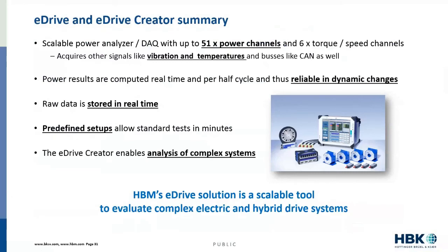So the eDrive creator really takes HBM's eDrive power analyzer another step forward in making it even simpler for users to do high-end measurements on complex systems without having to spend a lot of setup time to do things manually. Power results are computed in real time per half cycle, and you get very reliable results for dynamic situations.